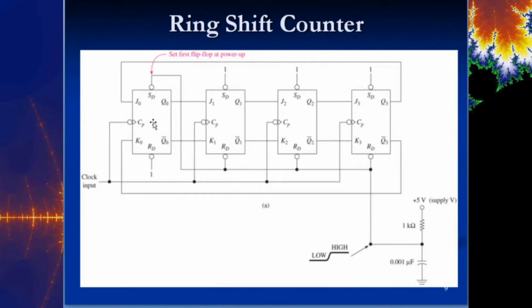Initially it's going to put a 1 in here and a 0 and a 0 and a 0. Now that Q, that 0 here, is going to come around to the front. And now in this case you'll have a 0, 1. You'll actually be in a reset condition, and that'll produce a 0 here. So what it'll do is push that 1 through to here. Now this output will be 1. That'll get clocked in the next clock cycle, and this one will become 1.